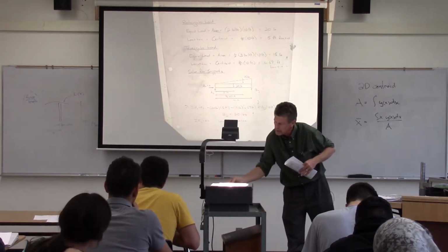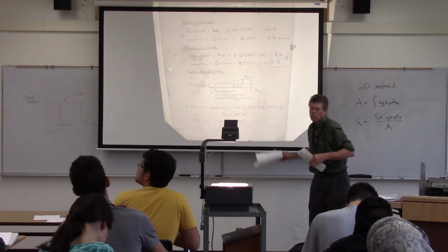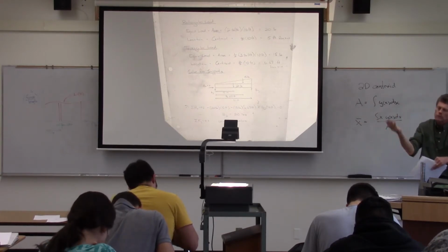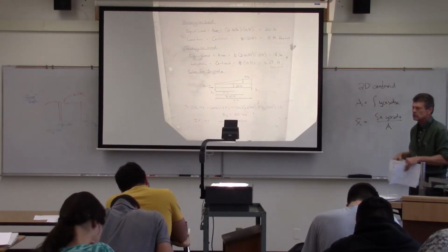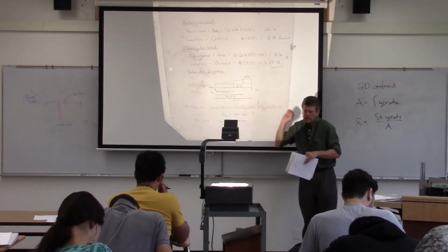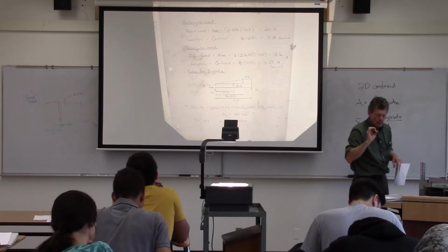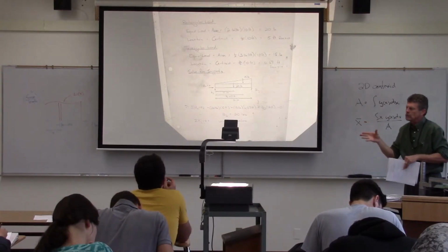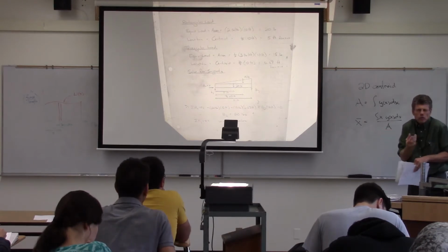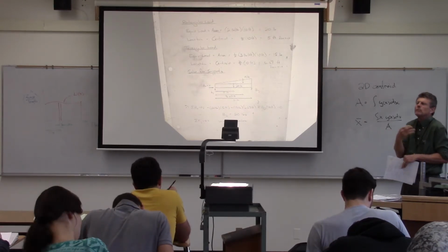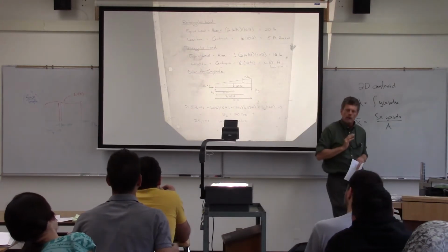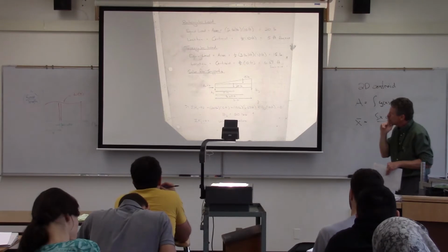So when I plug it into my moment equation, I just have an extra term. But that's fine. It's easier to solve that than going through solving for the resultant and then going in and just solving for one force there. So when we get to this equivalent approach, we generally want to just leave them as single forces because then we can just simply plug them into the moment equations. There'll just be extra terms in the moment equations, but it saves us a little bit of work there. We don't need to resolve it into one equivalent load in one equivalent location.